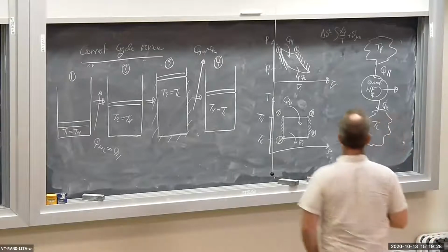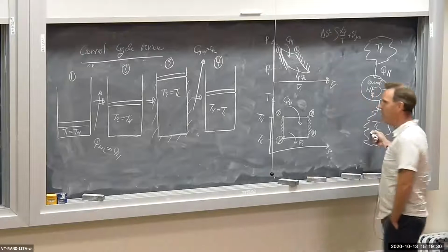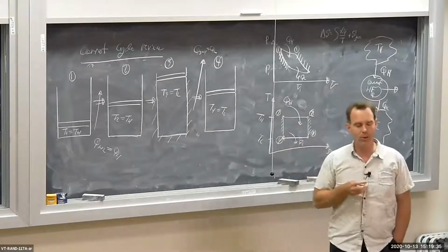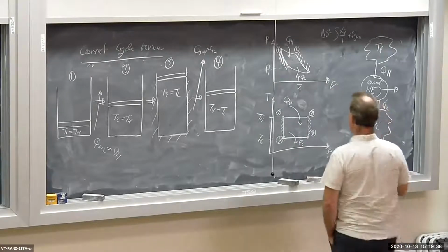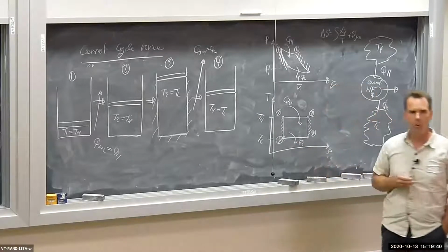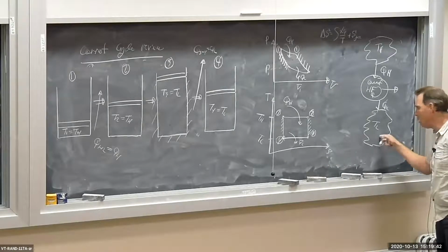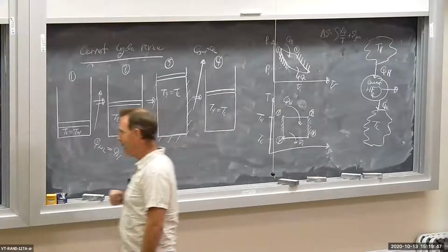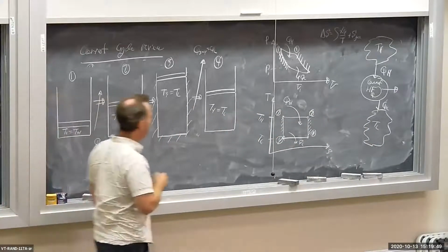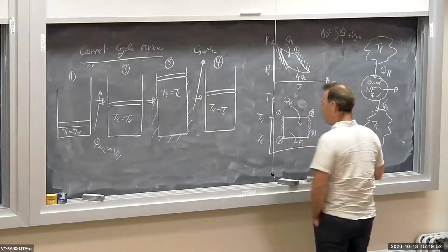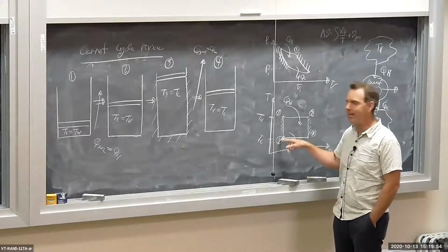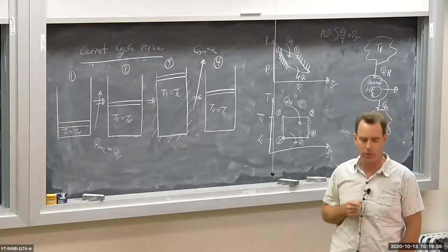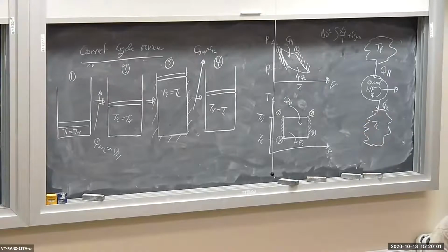Once we get to the low temperature reservoir temperature TL, we then proceed to compress the gas and reject the excess heat, QL, from the working fluid to the low temperature reservoir. Okay? And then to get back to state 1, we simply compress adiabatically and reversibly, compress the fluid back up to the high temperature state. And that gets us back to state 1, okay?